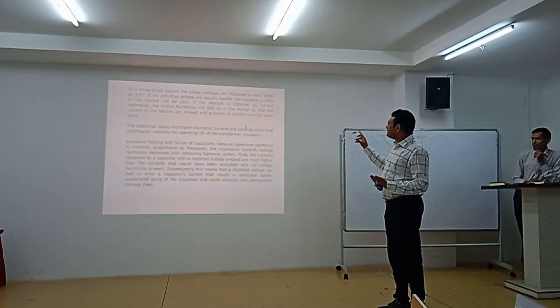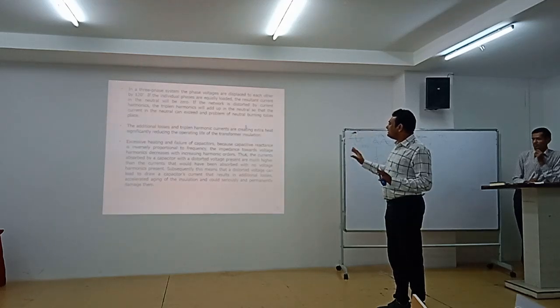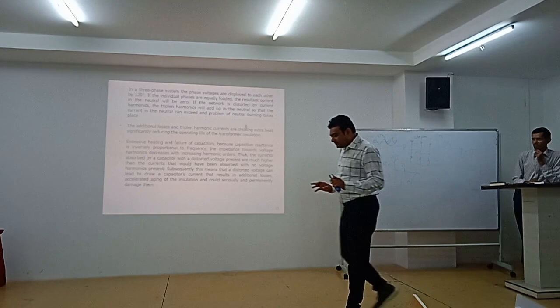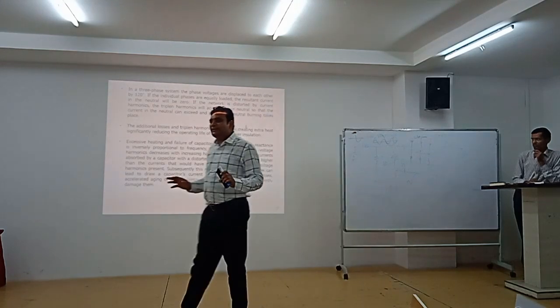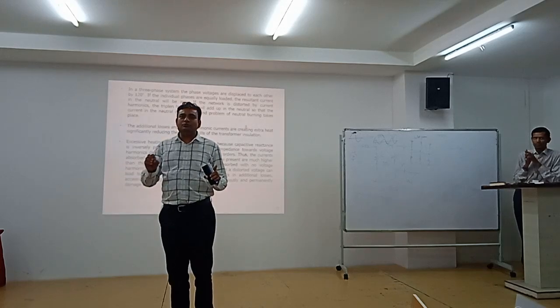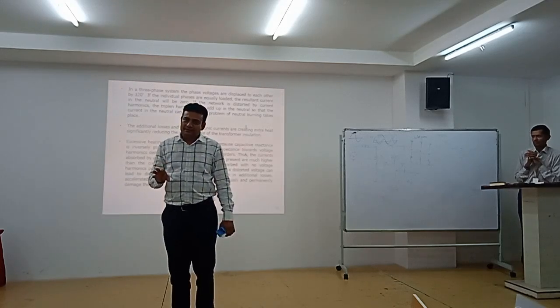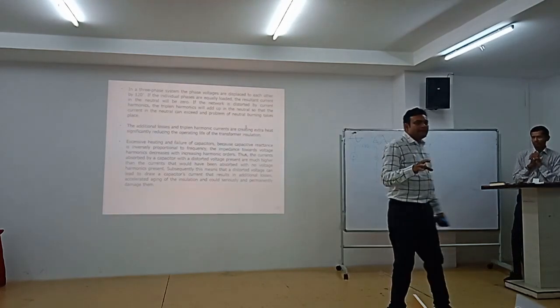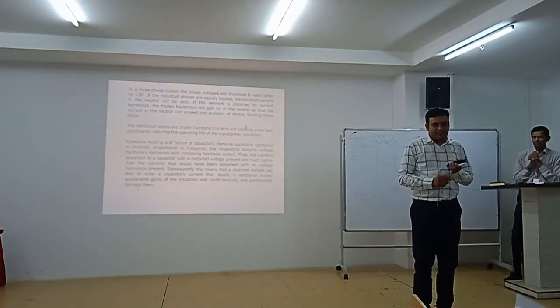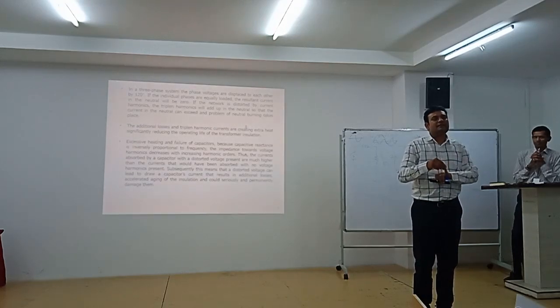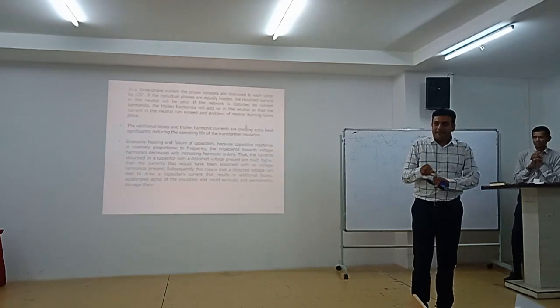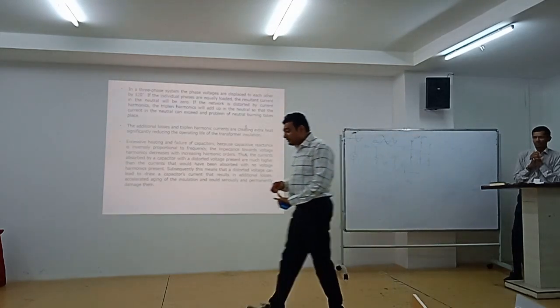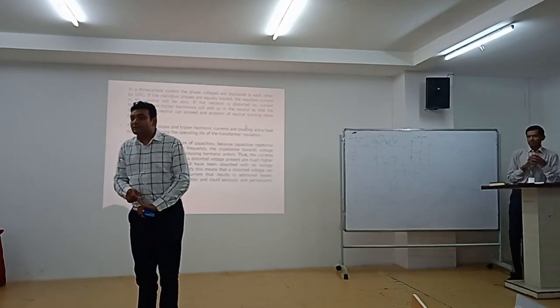Different harmonic currents are producing extra heat. All harmonics have a general tendency to heat up the equipment, whether it is a motor, generator or transformer. This is a natural phenomenon. So one thing is that it creates heat. The second thing is that skin effect is produced.